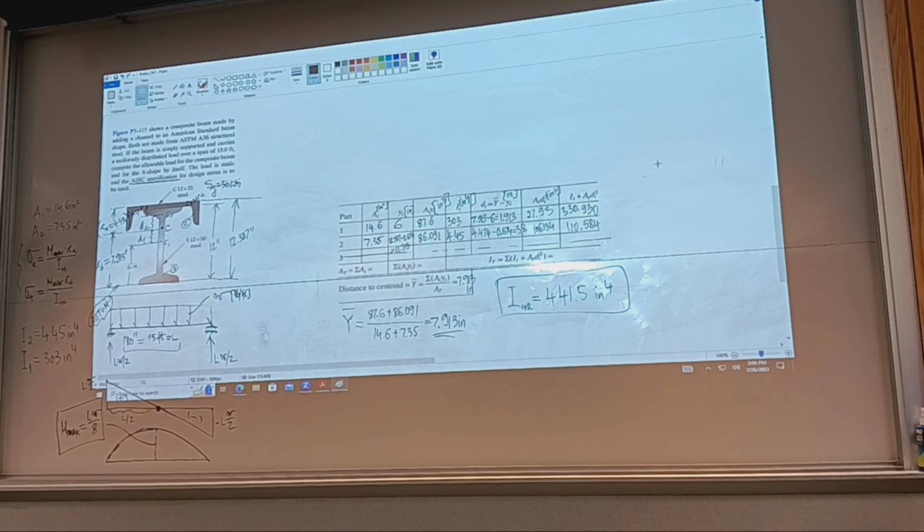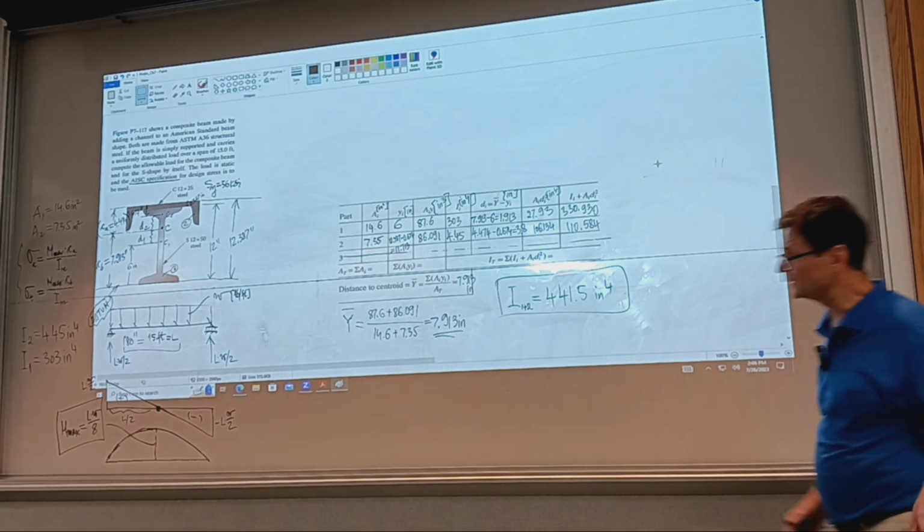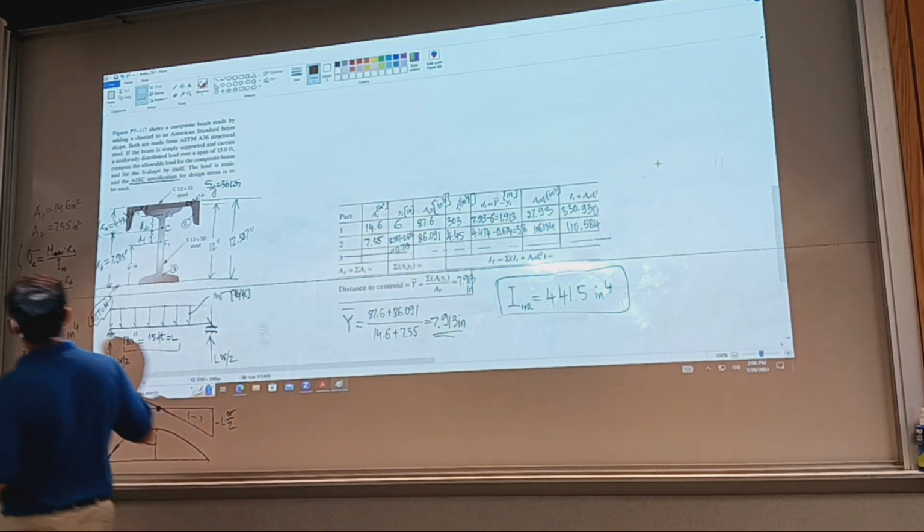Okay, so if you go to the back of the book where mechanical properties ends, it's page 790. We have design bending stresses, so general machine and structural design, and then B, AISC, American Institute of Steel Construction, structural steel, static loads, or building-like structure. It appears to be a building-like structure given the span, 15 feet. So for steel, the design factor is going to be 1.5, or 0.66, or we'll just say SY over 1.5. So design factor recommended